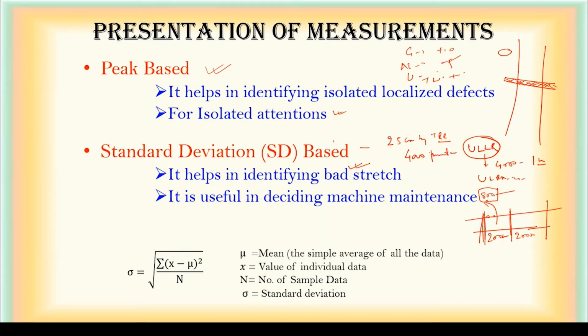So this parameter does not give you an absolute value. This I wanted to explain to you. This does not give absolute value. It gives the level of deviation from a mean value. Okay? Each kilometer is divided into 200 meter blocks, and for each 200 meters we get a standard deviation value of each defect. If a kilometer of track is more than 1,000 meters, then it may contain six blocks also. But normally it will be 200 meters, 5 blocks.